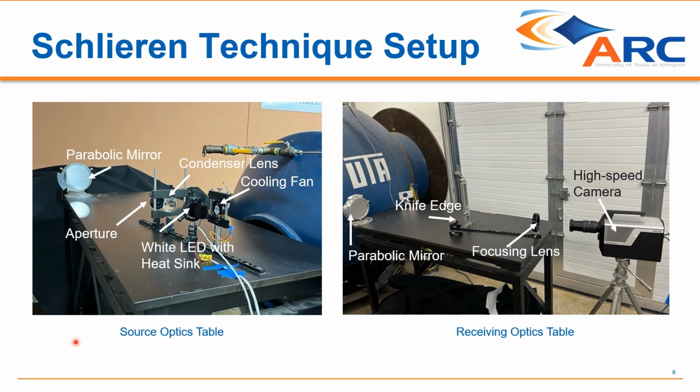You can see here our source optics table consisting of the high wattage LED, the condenser lens, and an aperture to only let the highest intensity light through, shining towards our first parabolic mirror. And then on the other side of the test section will be the receiving side, which has the second parabolic mirror, the knife edge here at the focal point, and the high-speed camera to capture the images.